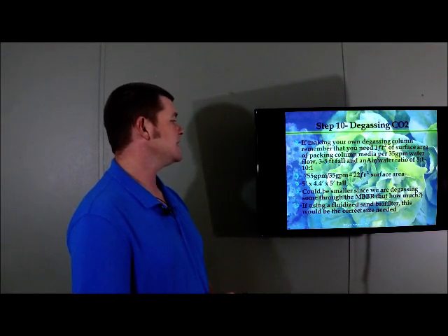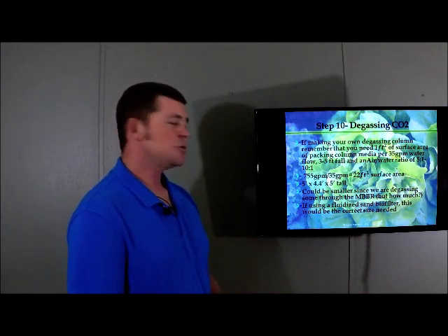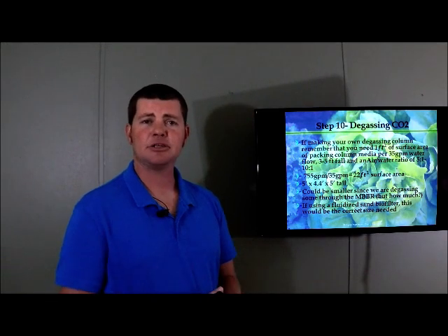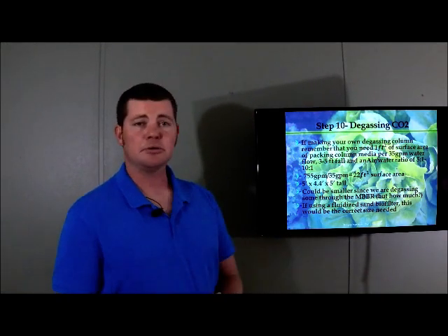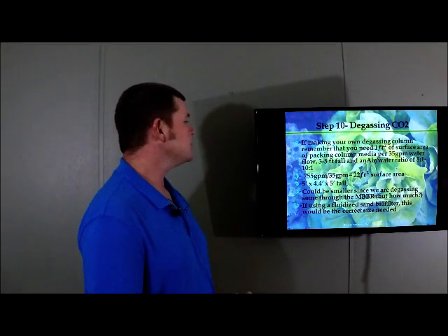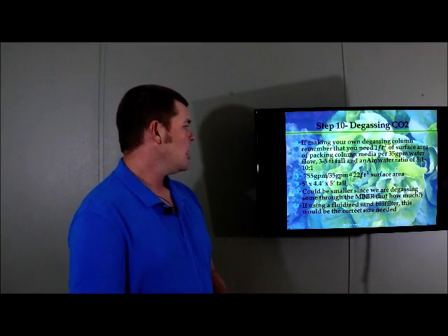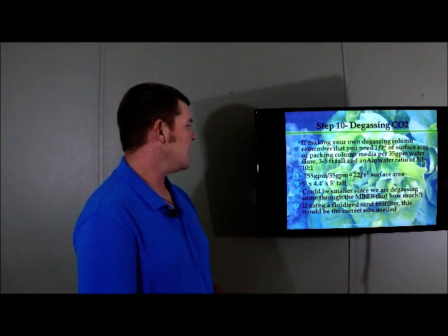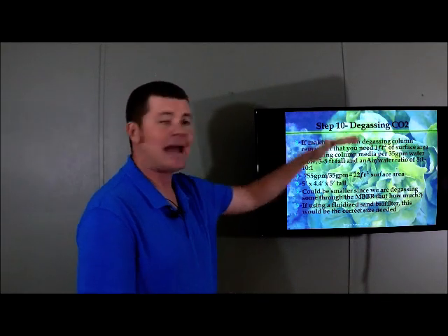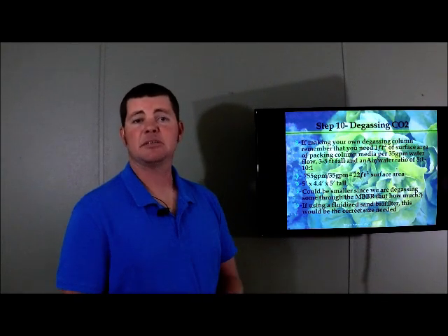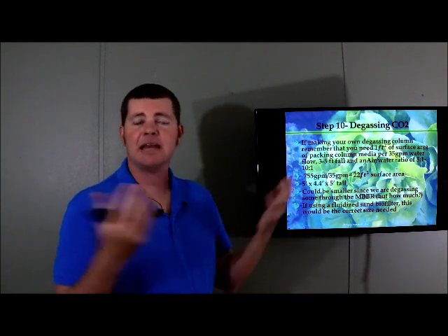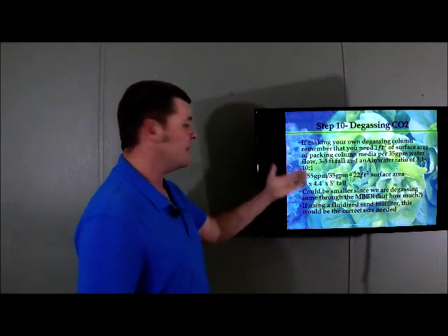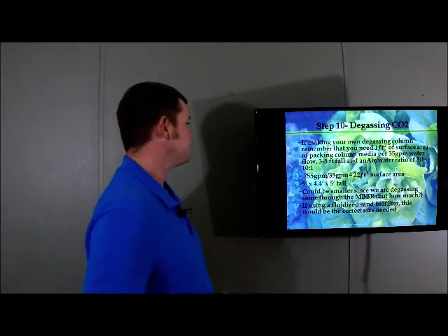If using a fluidized sand biofilter, which we don't talk about a ton in this because it's really used for a lot of large-scale operations, but it could very well be used in this application. If we were using a fluidized sand biofilter, this would be the correct size needed, okay? Because we're going to need to degas directly after the fluidized bed biofilter, and we're not getting any degassing out of that biofilter like we do out of an MBBR.